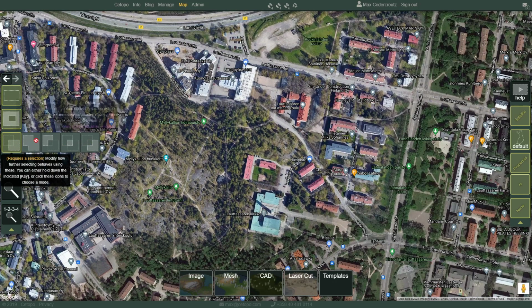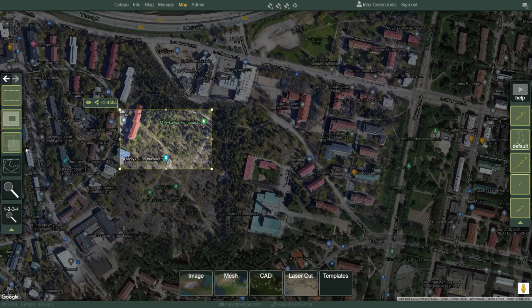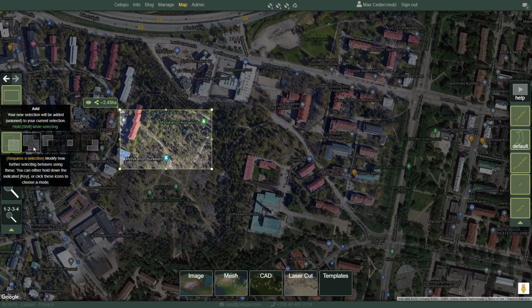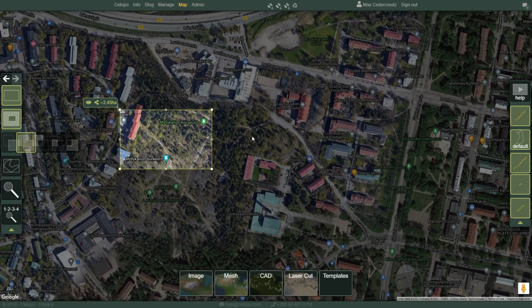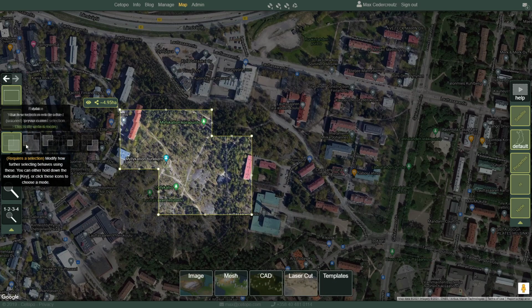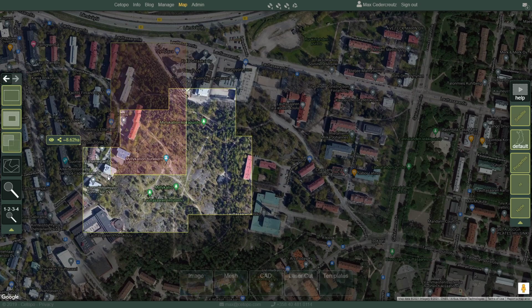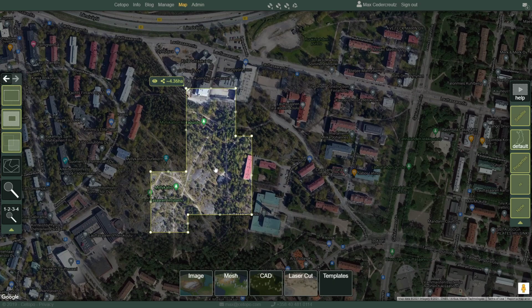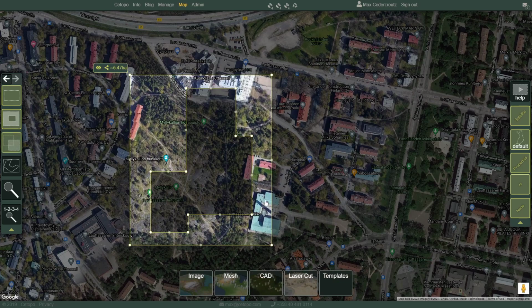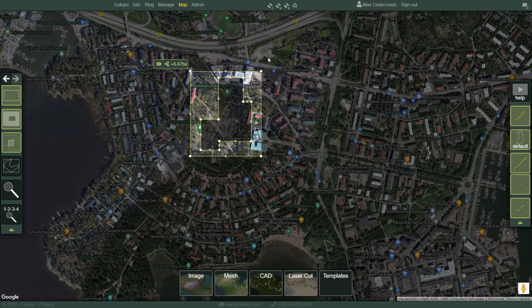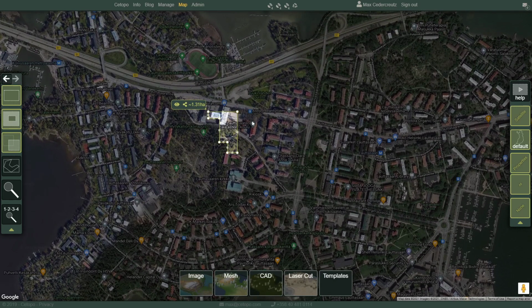The mid row here, this toolbox allows you to create complicated selections using modifiers. So you can either click these buttons here, for example, enable the add mode, in which case your selector will turn green and you can now add to your selection, or you can simply use the keys that are shown here. So for example, Shift will enable the add mode, Alt will enable the remove mode, Control will enable the intersect mode, and then Control Alt will enable the exterior mode, which allows you to get the exterior of a selection. And these can be combined to create any selection really.